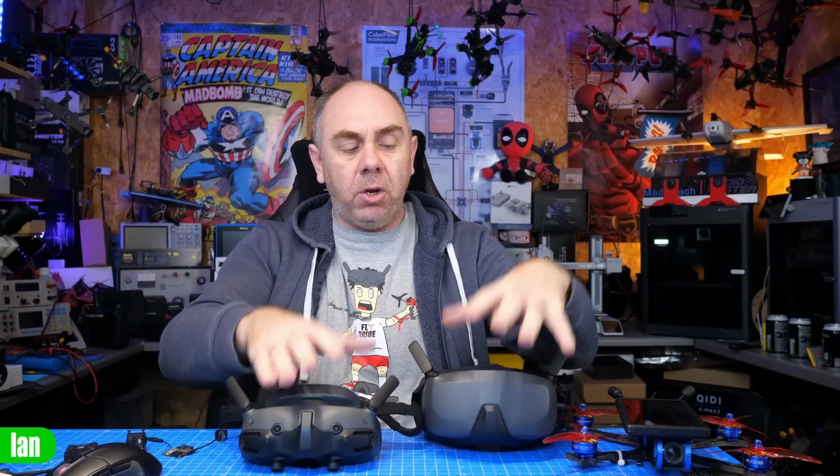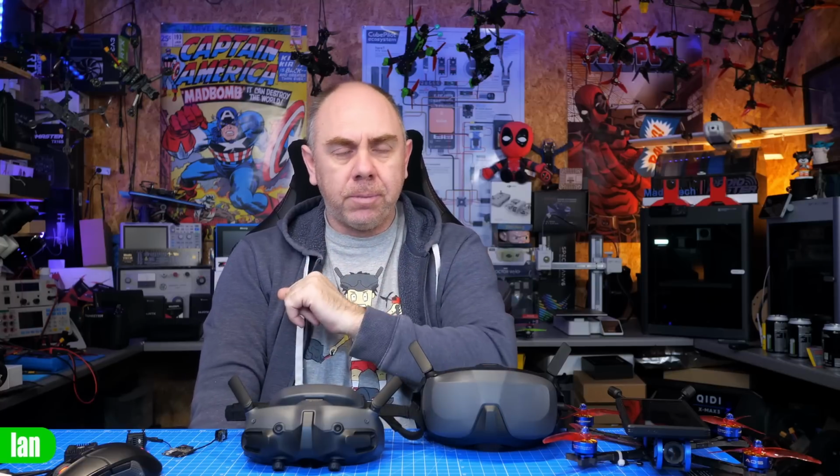Now, when it comes to the choice of goggles, there are obviously differences between these two. The N3 is a budget goggle. It is a single LCD display that is limited to 60 Hertz, whereas your Goggles 3 has your OLED displays capable of 100 Hertz. As a result of that, while both of these goggles will work with race mode, you're only going to get that low latency of 15 milliseconds on the Goggles 3 with regards to the Pro air unit, or 20 milliseconds on the Lite. You are not going to be able to get that low on these. The latency's a little bit higher.